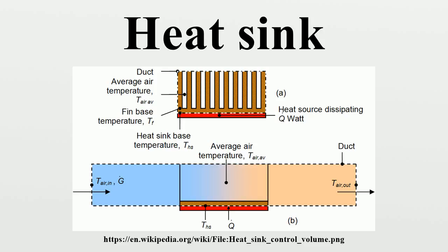Conductive thick plate between the heat source and the heat sink. Placing a conductive thick plate as a heat transfer interface between a heat source and a cold flowing fluid may improve the cooling performance. In such an arrangement, the heat source is cooled under the thick plate instead of being cooled in direct contact with the cooling fluid. It is shown that the thick plate can significantly improve the heat transfer between the heat source and the cooling fluid by way of conducting the heat current in an optimal manner. The two most attractive advantages of this method are that no additional pumping power and no extra heat transfer surface area are needed. That is quite different from fins.